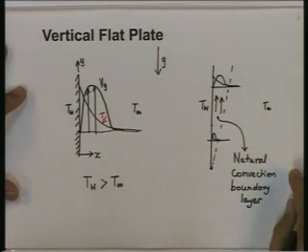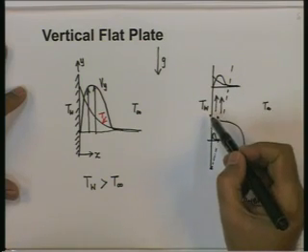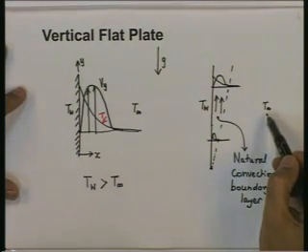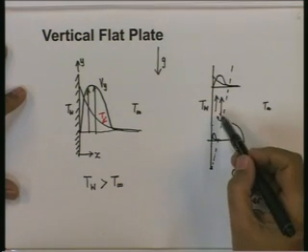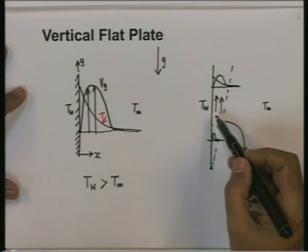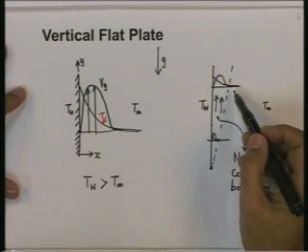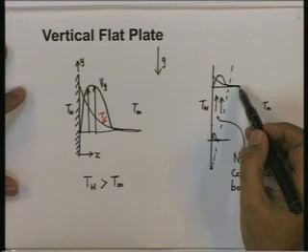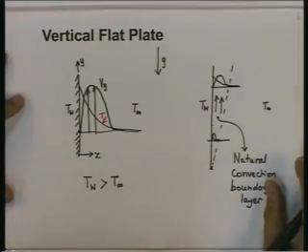It is similar to the forced convection boundary layer, but with the difference that this is the zone in which the temperature is significantly different from the free stream temperature. The effect of the wall is seen. Because the temperature is different, the density is different. Because of the density difference, there are buoyancy forces which cause local flow of fluid. In the free stream, the Vy will tend to be 0 because the bulk is not moving at all. It's a natural convection situation.